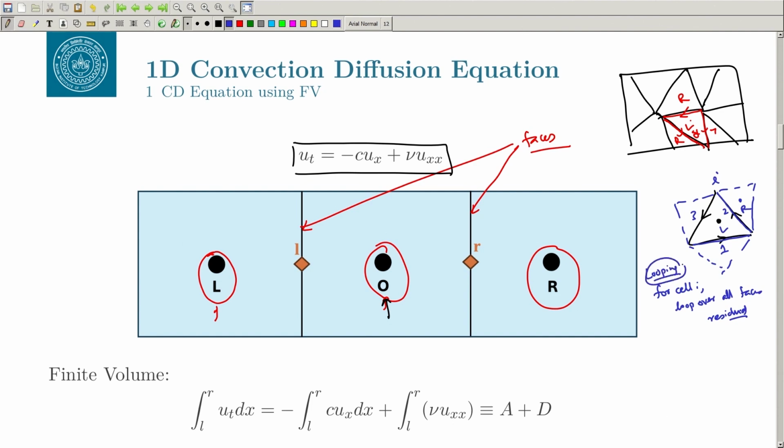What we are doing is we go to each cell one by one and look for the faces of that cell. Right now it is triangular, but you can have a quadrilateral face also. If you go to 3D, you can have hexahedral, prism, pyramids; you can have 3 faces in a certain cell, 4 faces in a certain cell, 5 faces in a certain cell. So that you need to see. Basically you have to go to each cell, find out the residual in each cell and sum it up, like we have been doing, sum of f perpendicular j delta s j, and you have to do this for every single cell. So the first approach is loop over cells, go through each cell, look for the faces and add that up. The other is loop over faces.